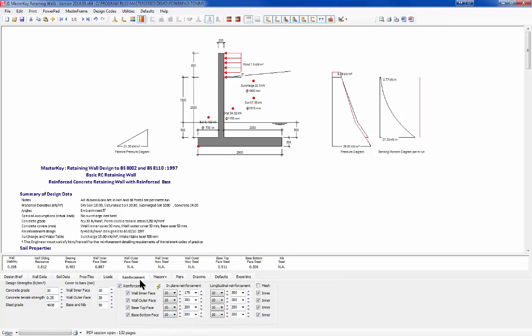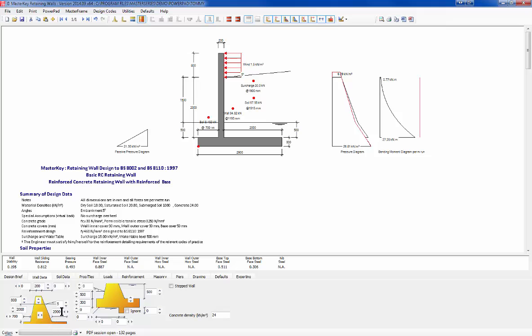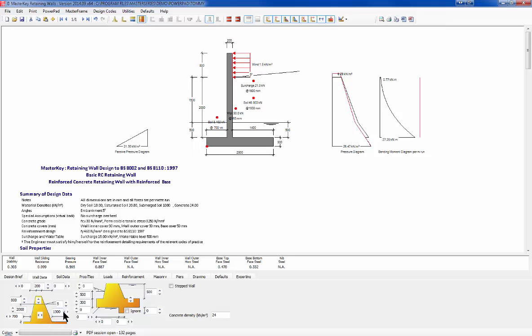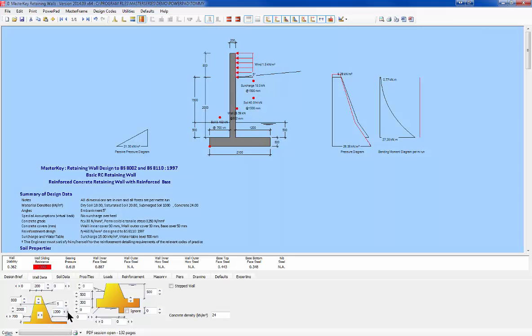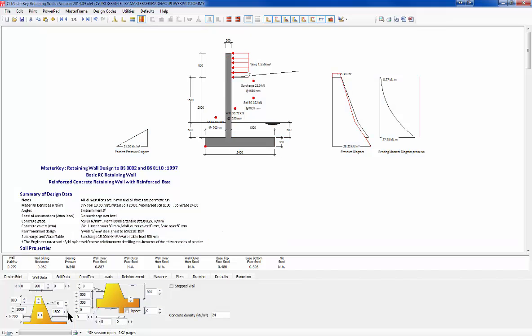And everything's designed. When I'm designing, I normally actually start from here and I take my size right in until it fails, and I say, right, geometrically, that is how big I want it to be. We'll just do that to make it a 2.5 meter long base. Now I've got it structurally sized, and then I'll go into my reinforcement. We've got our water table, as you'd expect.